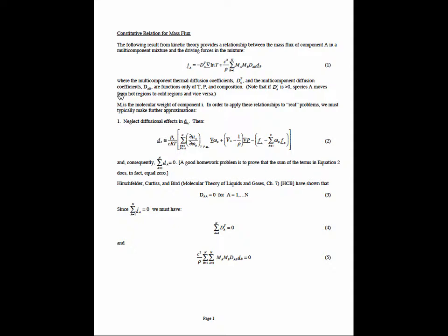temperature, and so forth. By far, the most important form of mass transfer in chemical engineering type problems is that driven by concentration gradients. And so we'll wade through some of this at least at a high level, but never forget that ultimately what we come back to using the vast majority of the time is that mass transfer is driven by concentration gradients. And so what this framework provides us is a thermodynamically consistent framework for describing how the driving force for mass transport affects the flux.